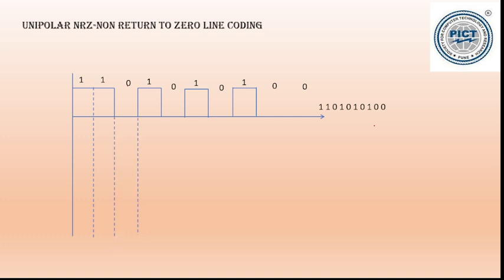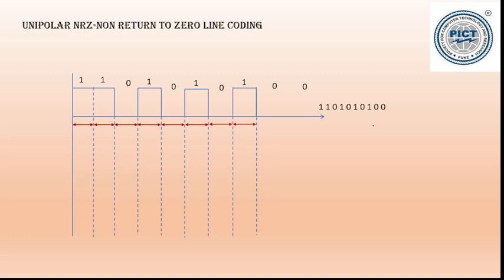Let us draw the propagation line to indicate the other parameters and the NRZ line coding. These bits having a time period of T seconds indicated here by T for each bit. So on the x-axis the time period is considered. On the y-axis the voltage level. So 1 is represented by +V and 0 is represented by 0.